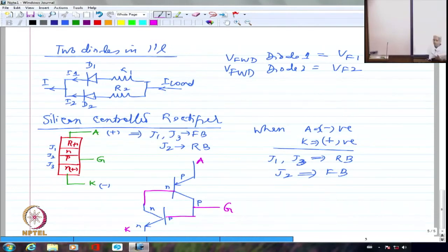That's one reason why thyristors or SCRs find an extremely large number of applications in rectifiers, not in inverters, not in choppers so much. Because with DC supply, it will be very difficult for us to turn it off. And inverters and choppers always have DC as the input. Choppers convert DC to DC and inverters convert DC to AC. So if I have input as DC, I will not be able to turn off the device, and that's one reason why I would like not to use SCR as much as possible in DC input circuits. Right? We would like to use IGBTs or MOSFETs or IGCTs or GTOs and so on. Those are used more in the DC circuits, not in AC input circuits. AC input circuits generally use SCRs or diodes.